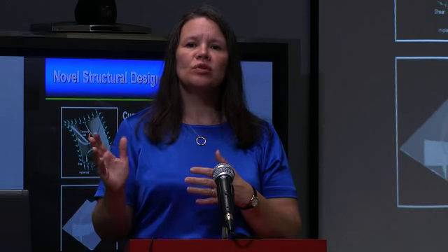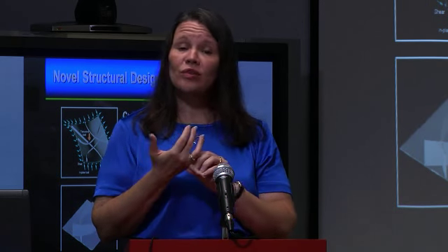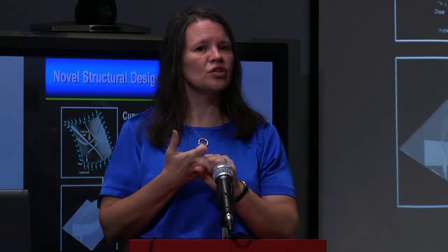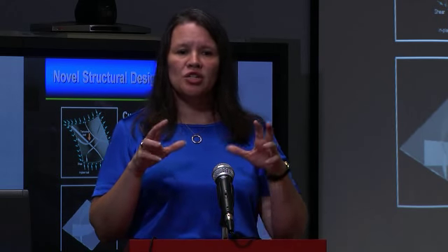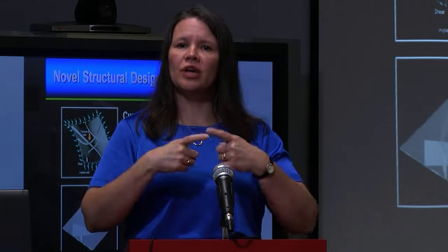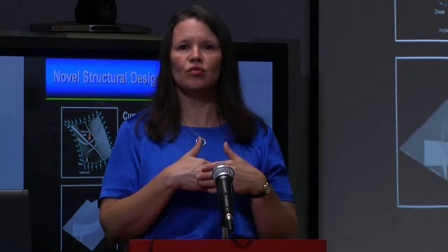And what can we do to design to improve the optimization of that design so that we can carry the load? One of the things that we've done is we've shown that you can carry the same load for less weight and actually change the acoustic resonance of that panel by changing the shape and location of those stiffeners. So a curved stiffener does not pass the acoustics. It doesn't ring the same as a straight stiffened panel. And so we've shown that we can reduce noise.